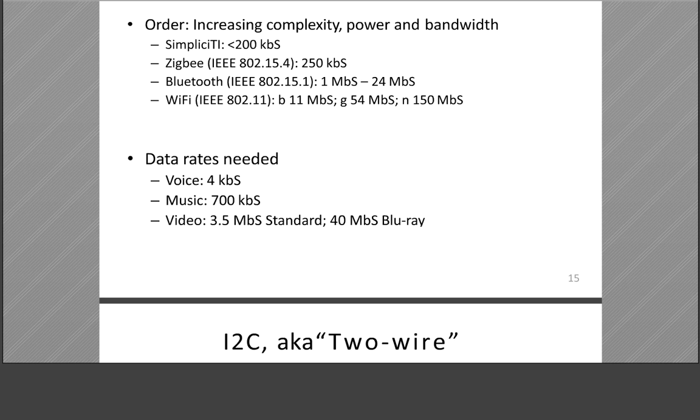For example, we put some guard band from 3 kilohertz to 4 kilohertz, so this is from 0 to 4 kilohertz, and then the sampling rate is 8 kilohertz, 8 kilo samples per second.